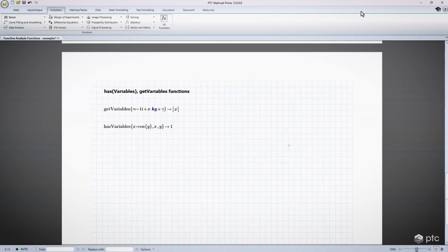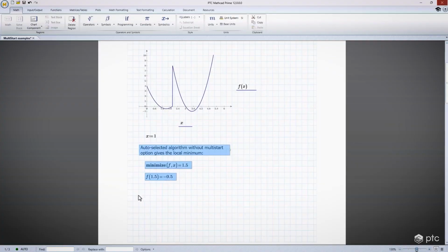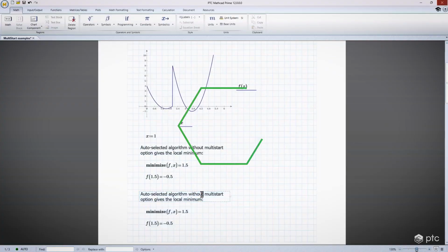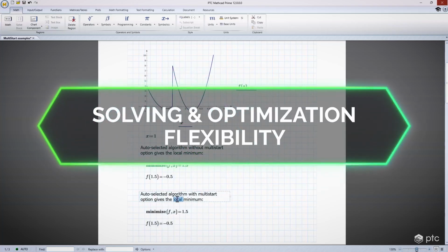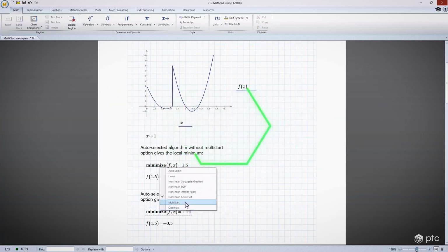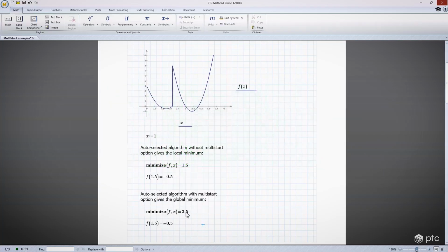Mathcad Prime 12 offers a triplet of engine features to provide more control and speed for solver functions. First, you can now right-click maximize, minimize, find, or minerr, and set them to MultiStart. This assists the solver to find a global solution rather than a local one.